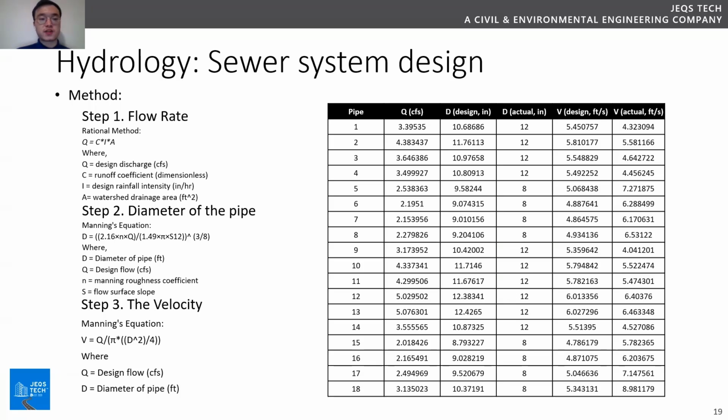So for the design of the storm system, the storm pipe system is a totally new system for this area because the existing pipe system may not be standard today. In this case, the existing system was ignored and not combined into our design. The whole project area was divided into several subcatchments in order to use the rational method to calculate the variables for the pipe. Meanwhile, the Manning equation is also important to calculate the size of the pipes and the velocity of the flow. The time of concentration used is 15 minutes for calculation.